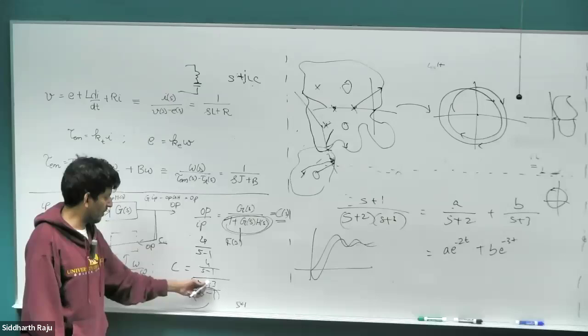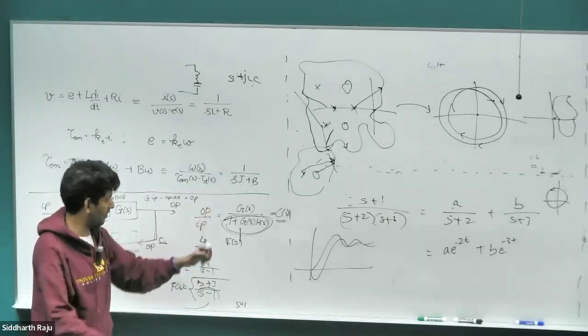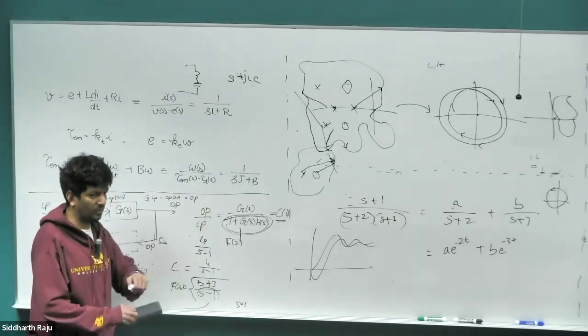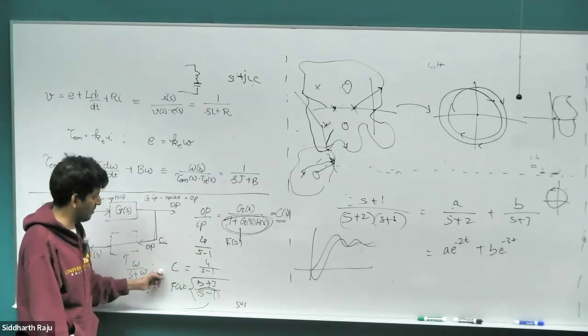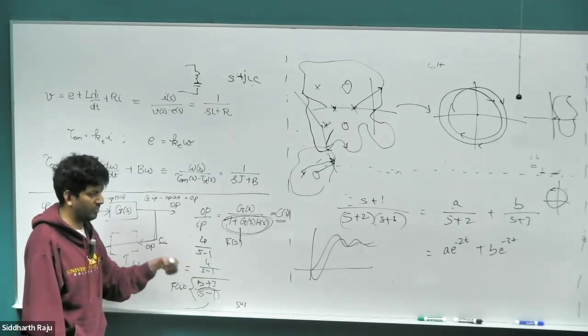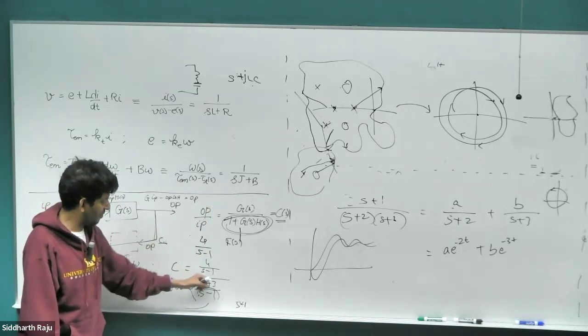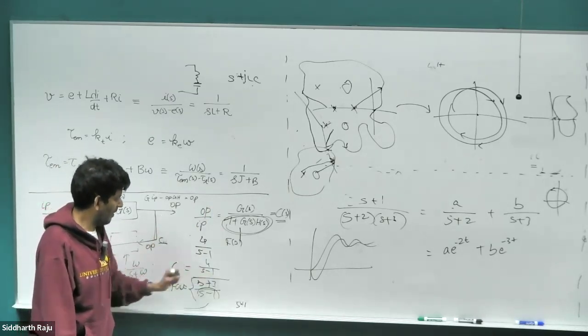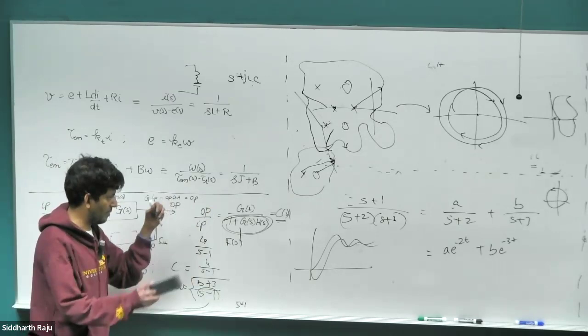So we already saw the zero, luckily, is not on the RHS plane, because if this had s minus 3, then the whole thing is done. It's a closed loop unstable system, because you have 4 divided by s minus 3 and the system blows out. But since we have s plus 3 in the numerator here, we are absolutely fine. We have a stable system.